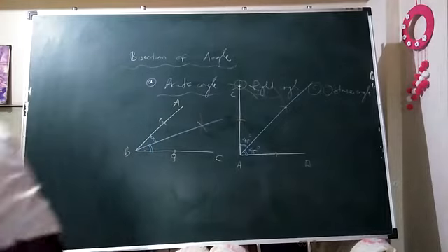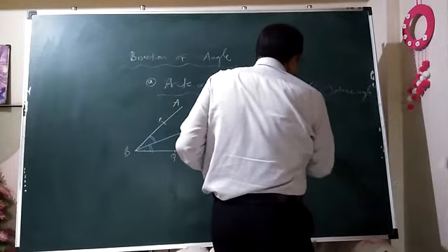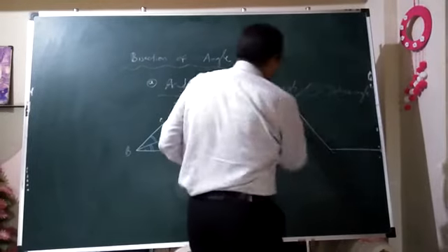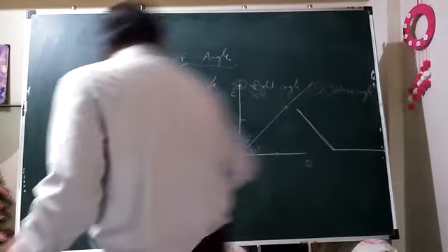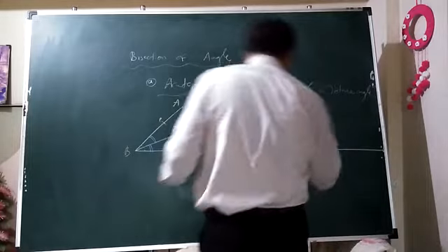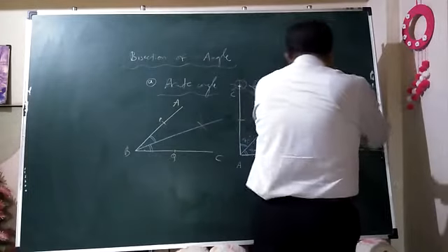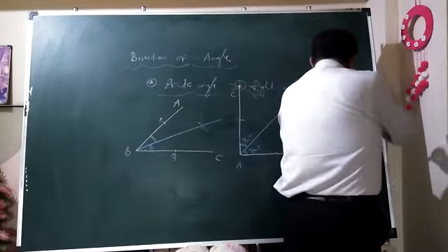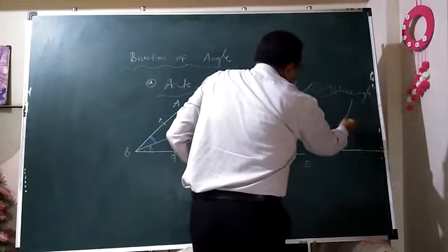Same way, for an obtuse angle, any obtuse angle, it may be 100, 120, any. First of all, you construct here any obtuse angle. No need to measure by using a protractor. Still, by the same trick, we are going to get its bisection. Same trick. Mark two arcs of the same radius and intersecting arcs from the earlier drawn arcs. In this way, you are getting space. This intersecting point is connected to this corner.